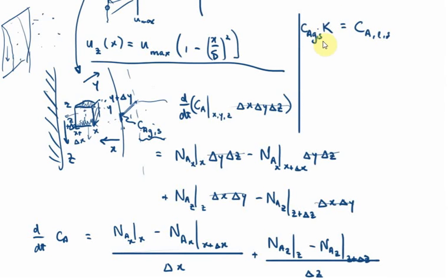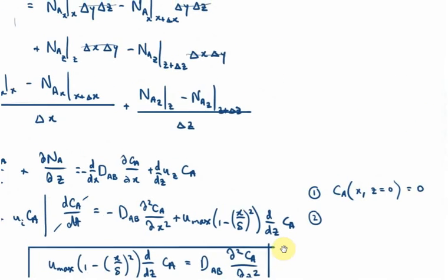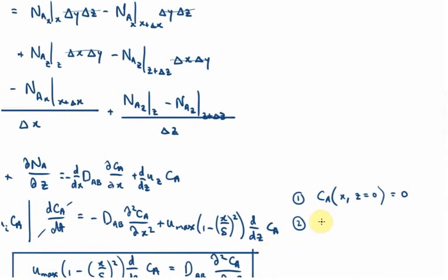Sorry about that. So we've got here in the gas phase the concentration near the surface, and then we use the equilibrium constant to translate that into the liquid phase surface concentration, and we're just going to call that CAS. So we can then identify that as a second boundary condition. So we can say the concentration of A near the surface, in other words, where x equals 0. Remember, we defined x from the surface looking into the film. For all z positions, that's equal to CAS.